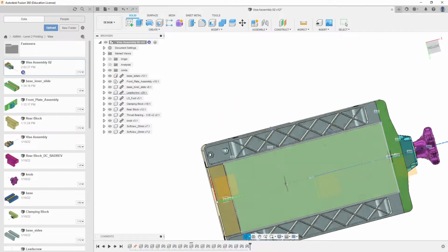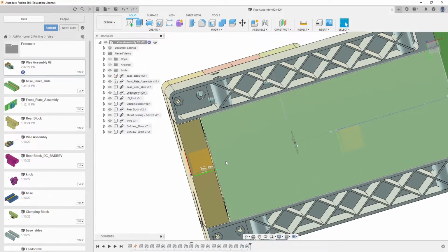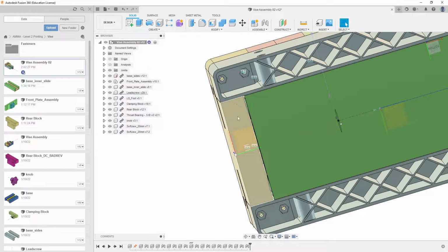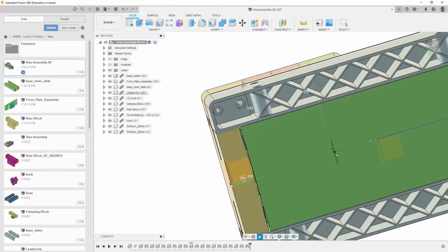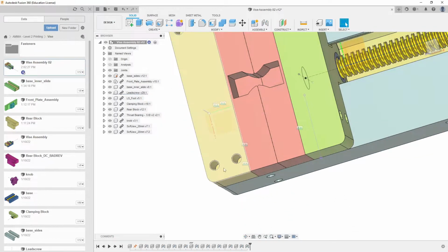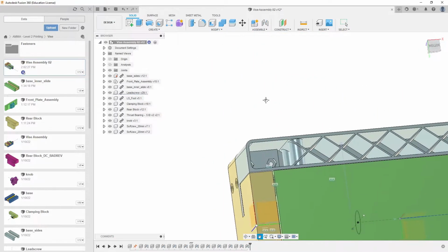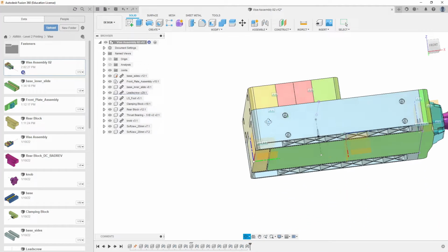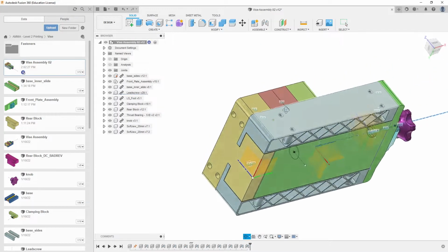Now, before I get started making that actual part, I want you to hold some stuff in your mind here as we move forward. This block, there's an interrelationship between, of course, all the parts here. If you look at this portion of this rear block right here, it has some holes on the top that need to go right through to these holes right here. Now, if there is any great discrepancy in our print, these will not line up.